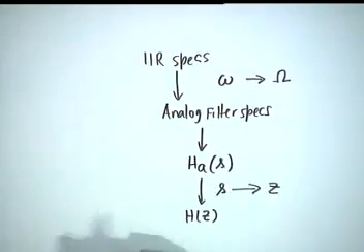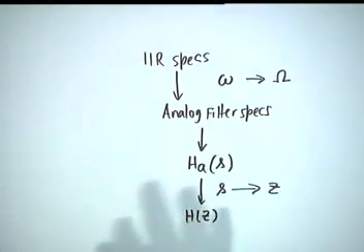we go through this analytical technique at all? Why can't you use a very blind approach? Like the specs are given, you estimate an order. Let us say from the given specs I estimate that a 10th order IIR filter should do. Then I require 20 unknown constants, 10 in the numerator and 10 in the denominator, of which the number can be reduced by 1. In the denominator, the constant can be normalized, so 19 coefficients, all right.